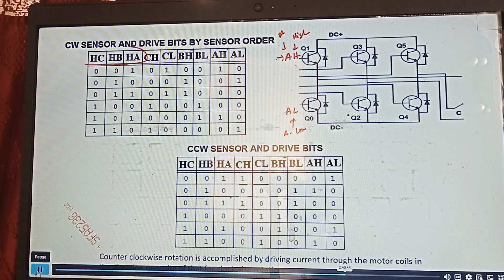And here you can see these are the three Hall sensors' data. As I told, in BLDC there are three Hall sensors. Each of them will give you just an on/off signal, right? Digital signal, 1 or 0. So ideally for 3 Hall sensors, you're supposed to get 8 combinations, but all 0 or all 1 will never happen because of their placement. So effectively you have 6 combinations. Out of 8, 2 are ruled out, so you are left with 6 combinations, right?